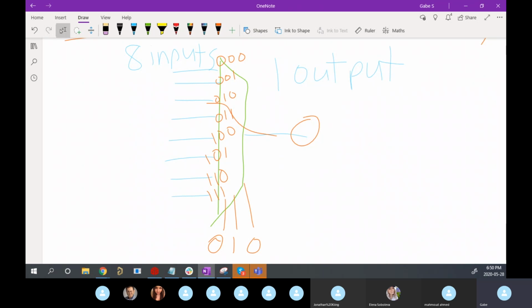And so we use a ton of these on the thermistor expansion board because it allows you to turn, for example, 8 to 1. So this is an 8 to 1 mux. Or you can get some that are 12 to 1, some that are 16 to 1. What's on ours? Do you remember, Jared? Is it 8? I think, yeah, because I think we have 12 total on our board. Yeah, I think we have 8. Yeah, so on our thermistor expansion board, we use this one.